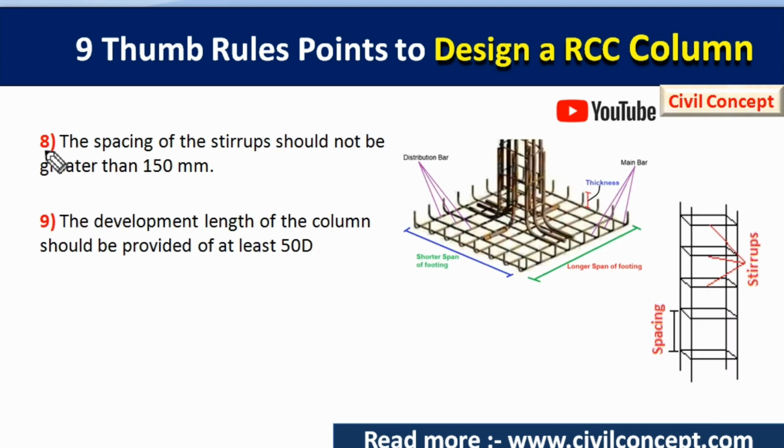Now point number 8 is the spacing of the stirrup should not be greater than 150 mm. You can see in this column, these are the stirrups. These stirrups have been tied at some spacing. The maximum spacing should be how much? 150 mm. According to design you can decrease the spacing between the stirrups, but the maximum spacing of the stirrup should be 150 mm.